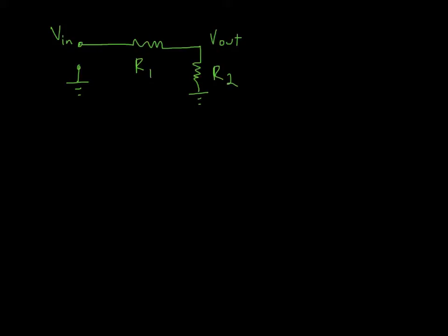All right, and so what we'll find soon after we move off of DC circuits is these components here can be more interesting. They can change with frequency, and they can make filters and all kinds of other interesting circuits. So the first step is let's find some current in this circuit. Again, what we want to find is some relationship between V out and V in. And so the first thing we're going to do is let's just find I.